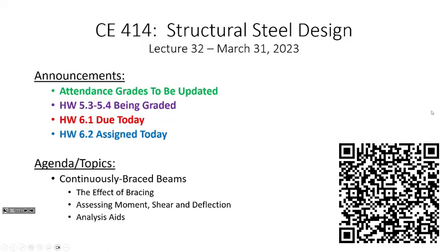So it might show up on an exam, but it probably isn't going to show up in any more homework assignments. But the cool thing about it is, if it does show up on an exam, it's easy. It's really not that hard. Just find the line where the area above equals the area below and just start summing moments about that line, and there you go.